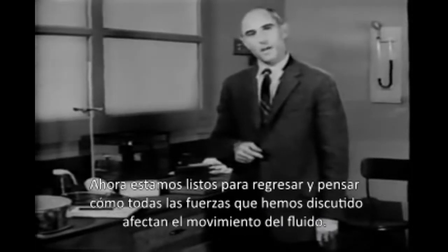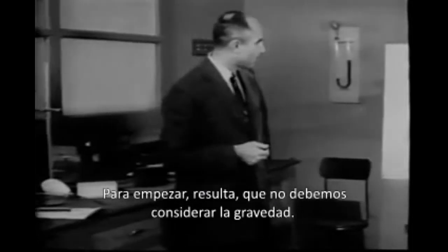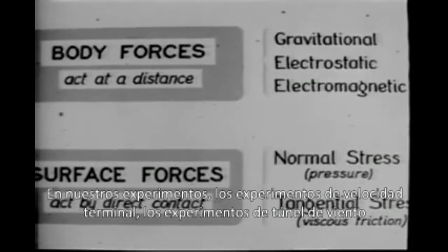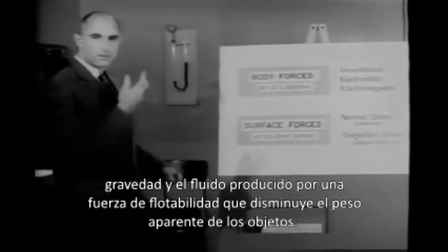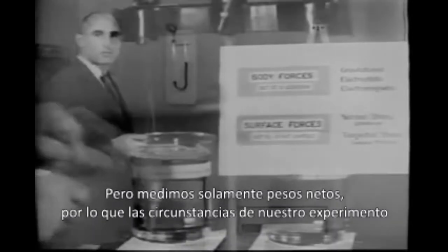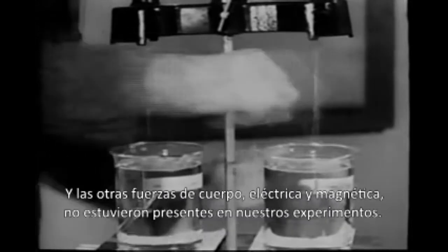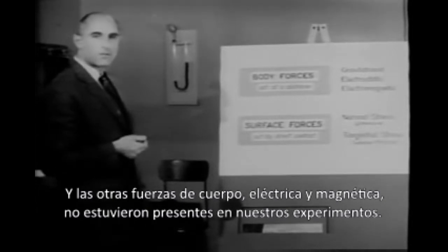Now we are ready to come back and think about how all the forces we have been discussing affect the motion of the fluid. First of all, it turns out that we need not consider gravity at all. In our experiments, the terminal speed experiments, the wind tunnel experiments, gravity in the fluid produced a buoyancy force which decreased the apparent weight of the objects. But we measured only the net weights, and so the circumstances of our experiments were such that gravity was automatically compensated for. And the other body forces, electrical, magnetic, were not present in our experiments.